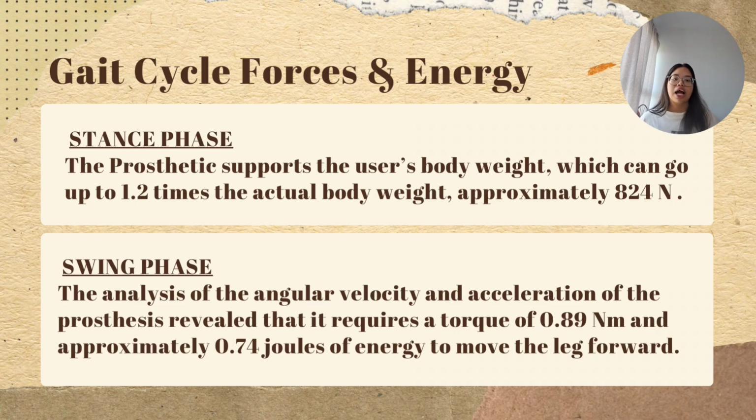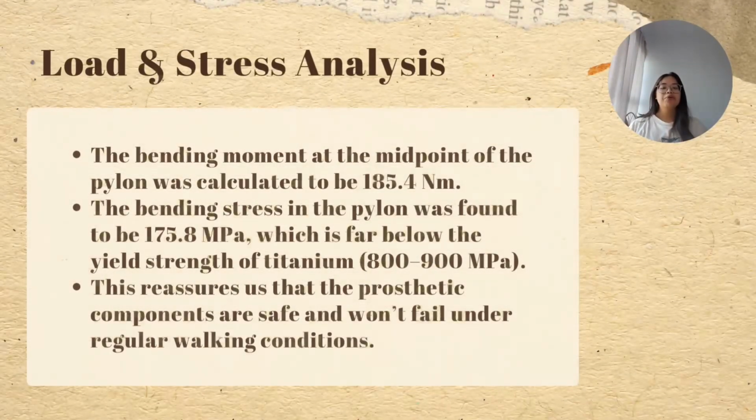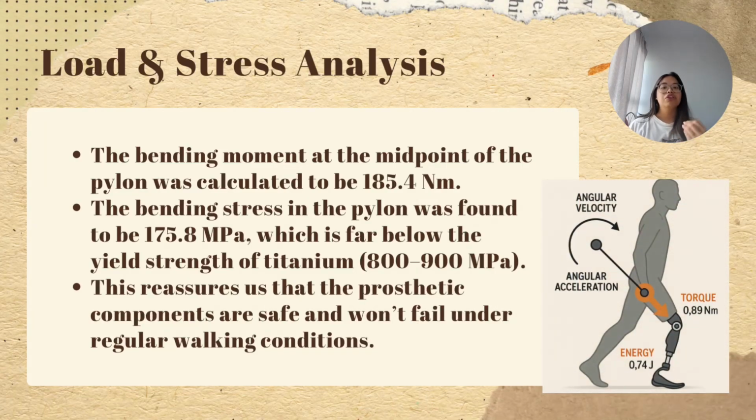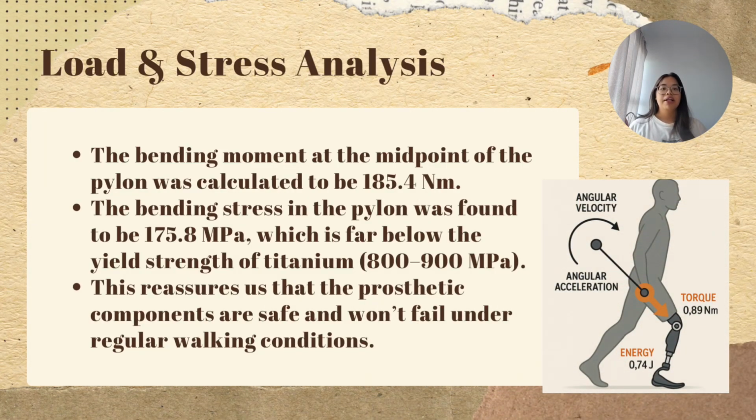To better understand how the prosthesis handles forces, we constructed free body diagrams of the socket, pylon, and foot, which helped visualize the roles of gravity, ground reaction, and inertia. Another objective we had was to determine the axial, bending, and torsional loads acting on the prosthesis.